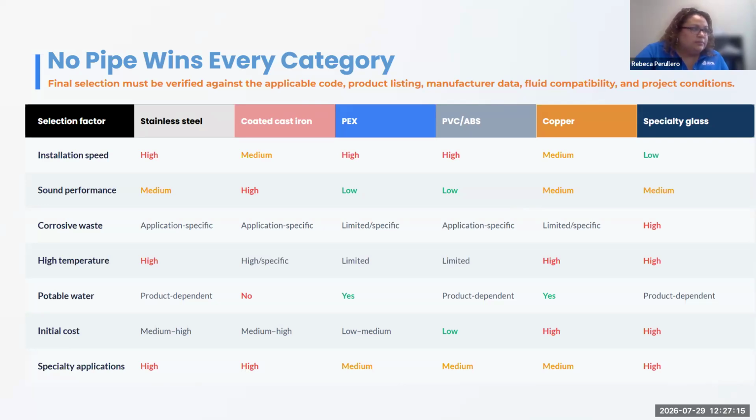And I want to comment as well on high temperature. In certain applications, say healthcare or long-term care, you're doing a high temp flush to control for Legionella. Even in general, we are distributing at higher temperatures these days than we did in the 90s or early aughts to control against Legionella, even in your most regular applications.